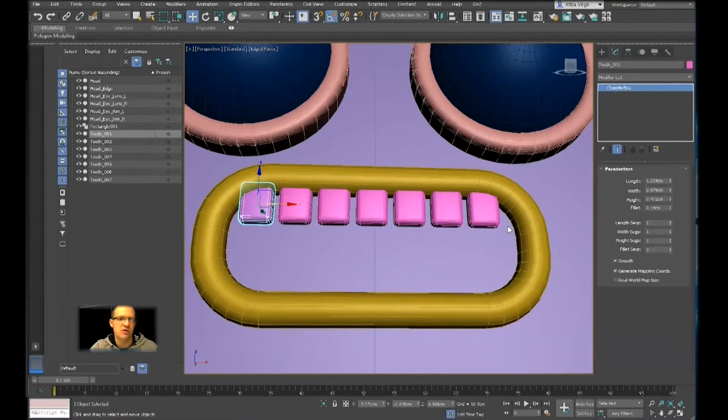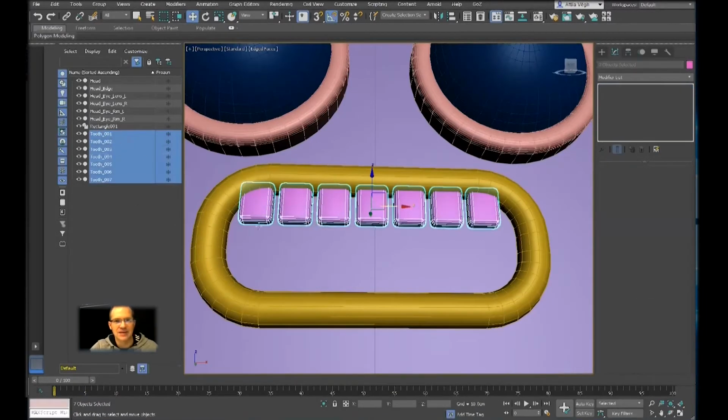If you are pretty accurate with the naming, usually it's a good idea to use shift and the name. So here's the name, click on the first, hold down shift, and now everything that is a tooth is selected. Or if you have hundreds of elements, but you know the name, you can go up here in this location dialog, type in tooth and hit enter, and now we have all the elements selected.